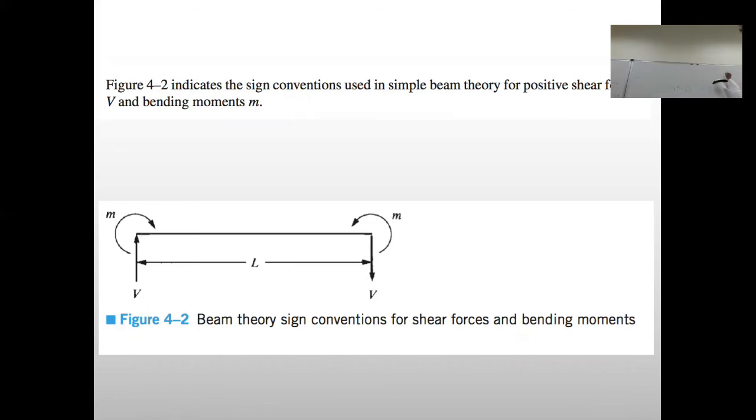If you have a beam and you make a cut here and a cut here, what is the shear and moment? Take this element. What is the shear here? Is it down or up? Down. What's the moment? This way. Okay, what about in the left-hand side? Up, and that is exactly what you see here.